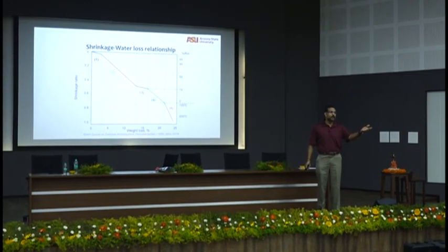It might crack because of overloading. It might crack because somebody dropped a steel ball on it. Yeah, you can't help that. But shrinkage cracking is unlikely because the humidity is always kept high. You see that? Very high humidity.